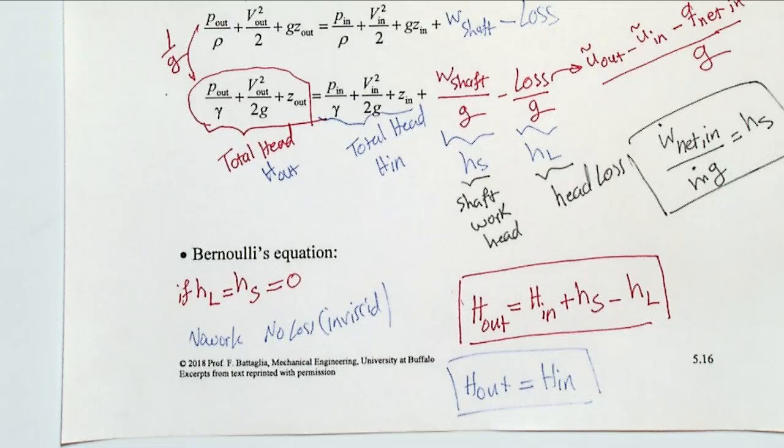Why do we need that? Because conservation of mass relates the input and output and gives you one equation, if you don't know the input or output velocity. And conservation of momentum by itself has 2 or 3 directions. We are talking about 2D mostly here, so it gives you 2 equations by itself, and conservation of energy is also 1 equation, right?